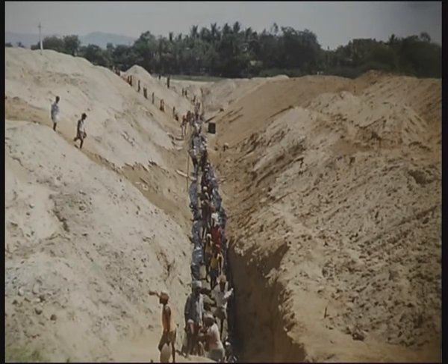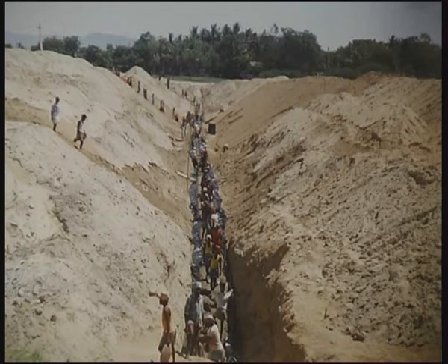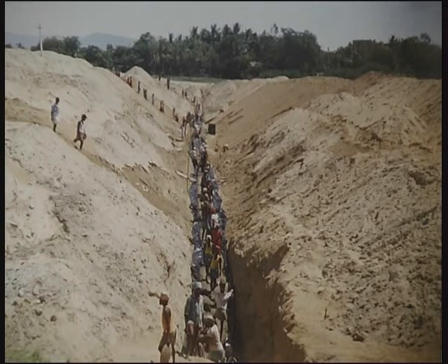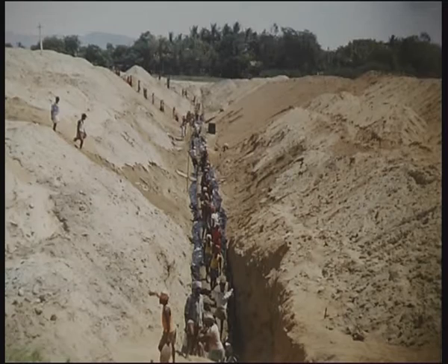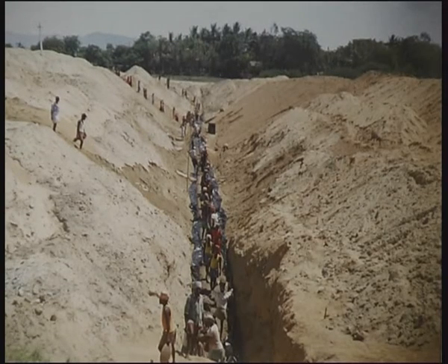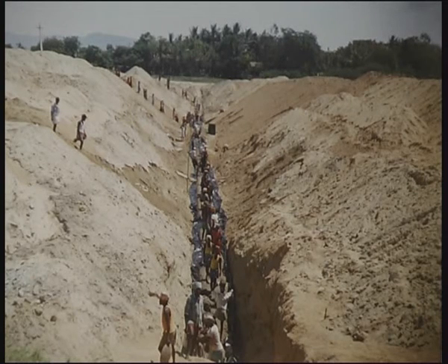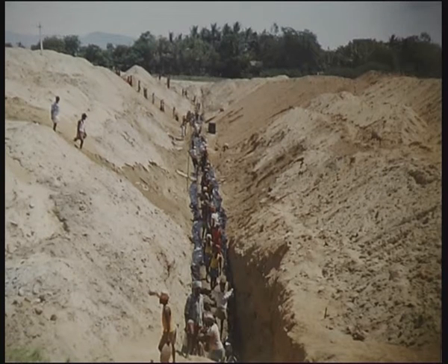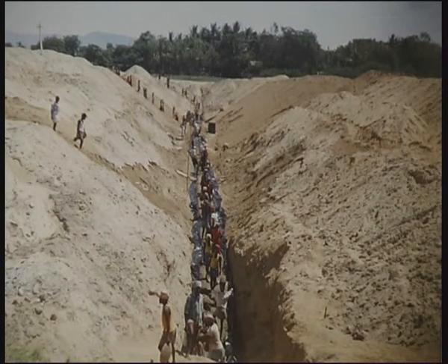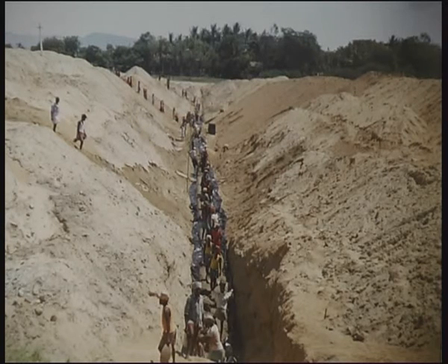In the case of a watershed development work, we increase the recharged water table and increase the groundwater content in the watershed. This groundwater would find its way into the stream and further down to a lower area at a velocity which would be much less when compared to surface water.